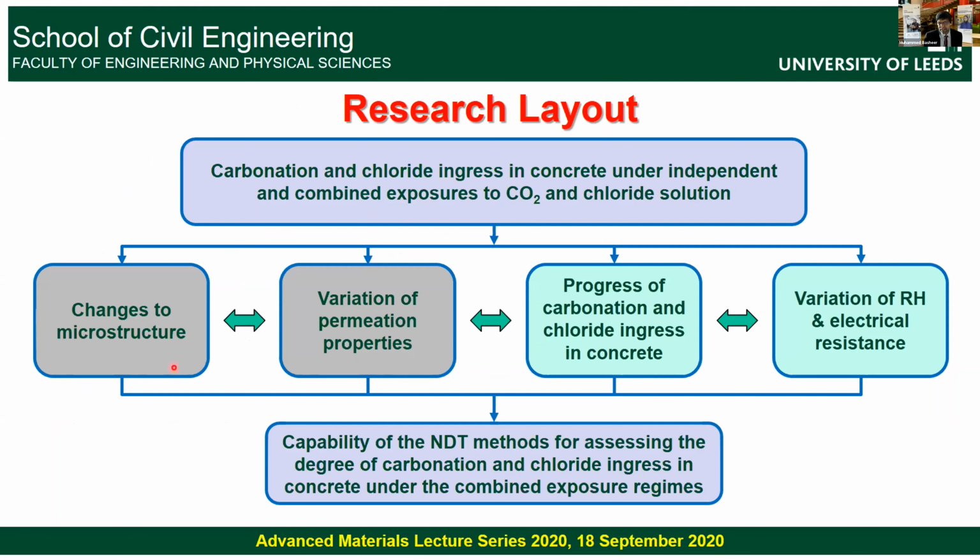We'll be looking at the microstructure. We'll be measuring permeation properties. We'll be looking at the progress of carbonation and chloride ingress, and also the variation of the electrical characteristics of the concrete. And using all of them, the capability of NDT methods for assessing the degree of carbonation and chloride ingress in concrete under the combined exposure regimes will be arrived at.